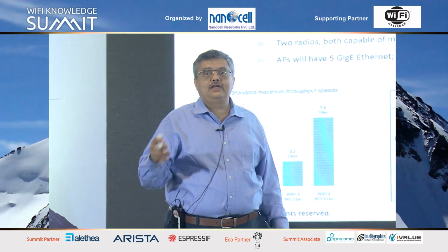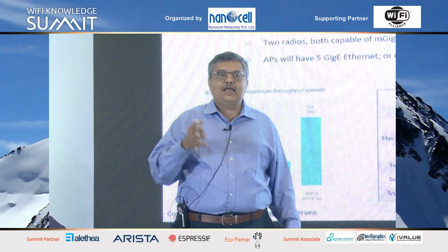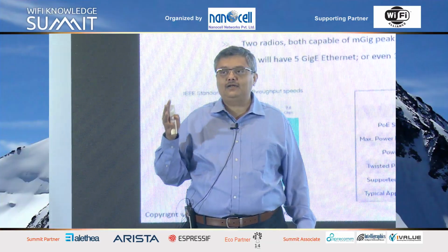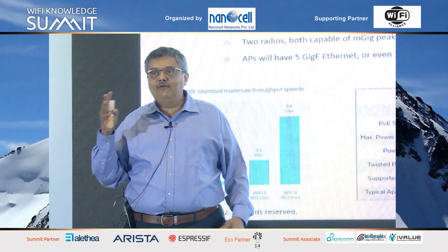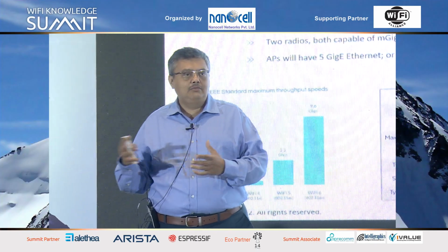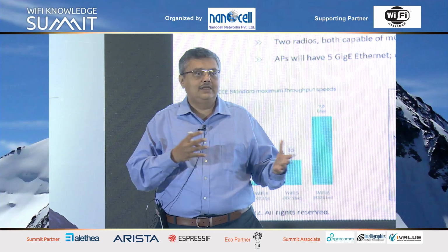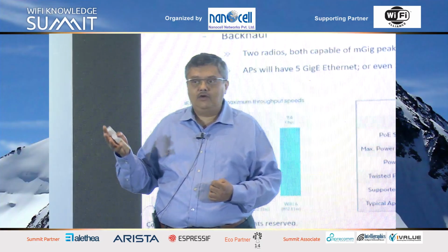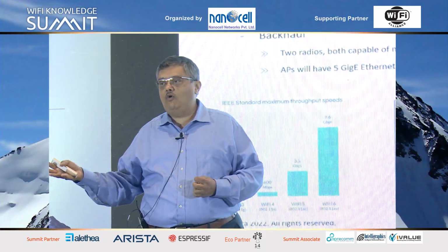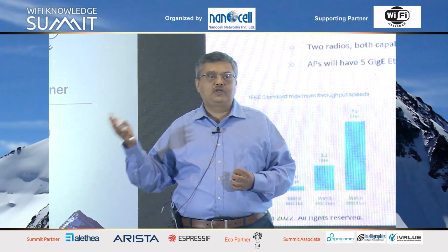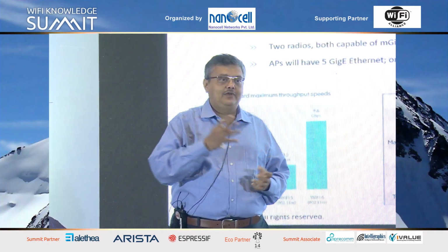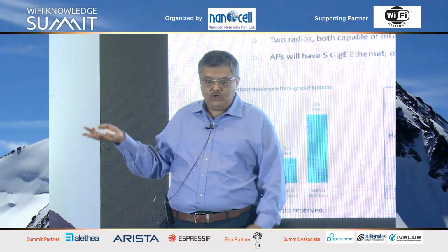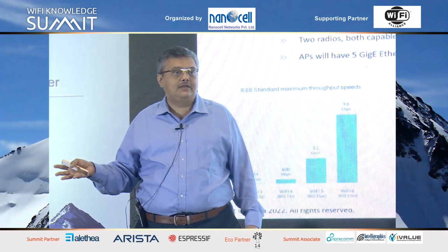One of the other things that we realize is really, really key is actually the cables that have been laid out, right? We've seen that a lot of people, even though their cabling was fairly new, maybe 2, 3, 4 years max, because that is when they had replaced their switches, have Cat 5e. Now, if you want to drive 60 watt power from a switch over 100 meters, and make sure that you don't heat up your plenum and stuff like that, you should have Cat 6a cabling.